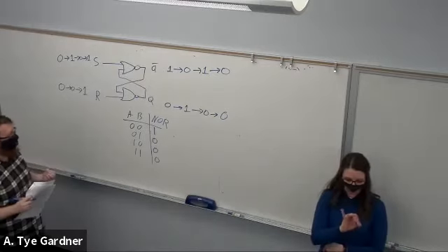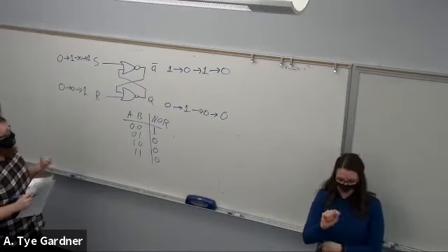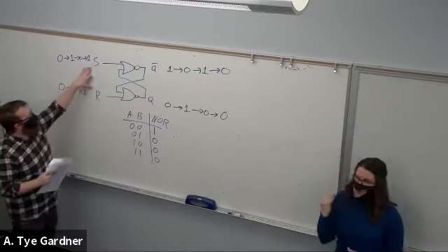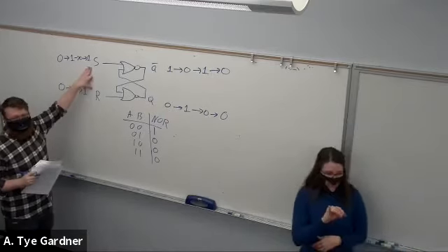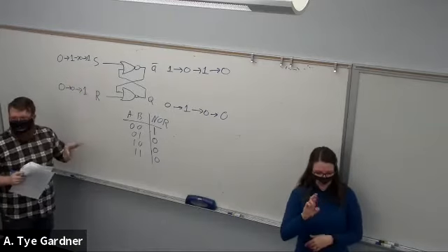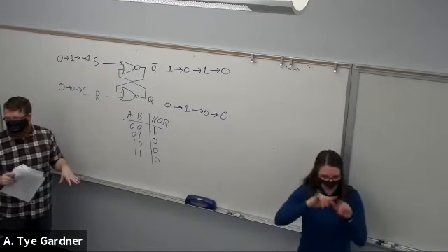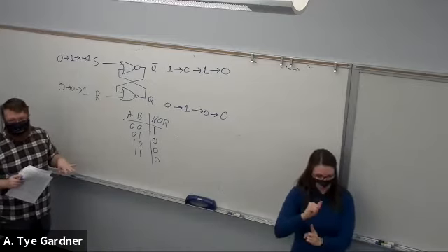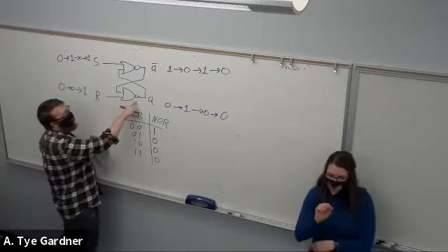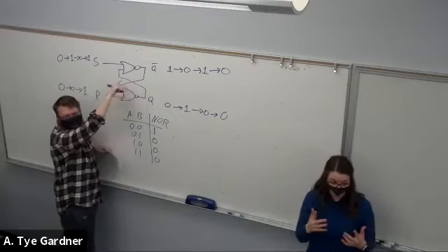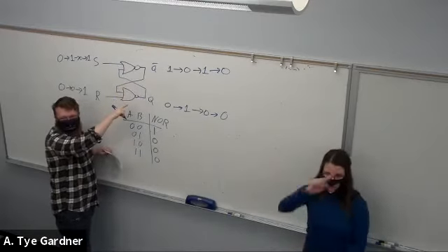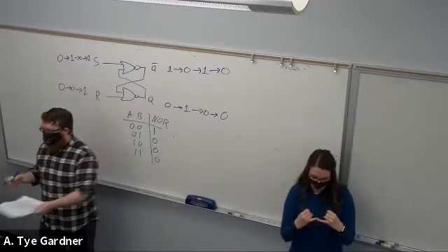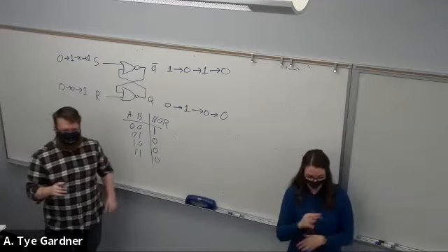And the risk is, what happens if I deassert both of them? Meaning I take them both from 1 to 0 at the same time. We're no longer setting, we're no longer resetting. And what's going to happen is you're going to have kind of 1s chasing each other around in this circuit. And you're going to end up in what we call a metastable position.